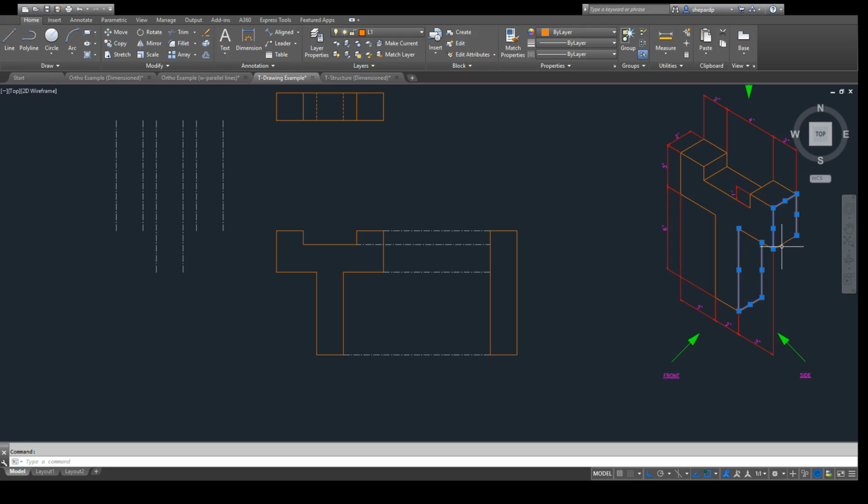Now I need to get this line right here, which I know is 6 inches, because it is the same as on this side. So this line right here, I can follow this projection line. It is 6 inches from the base, which we can check now. 6 inches. All right. Finally, we got to draw this inside edge line, which I can't see. It would be the line going like this, or this line. I can't actually see that from the right side.